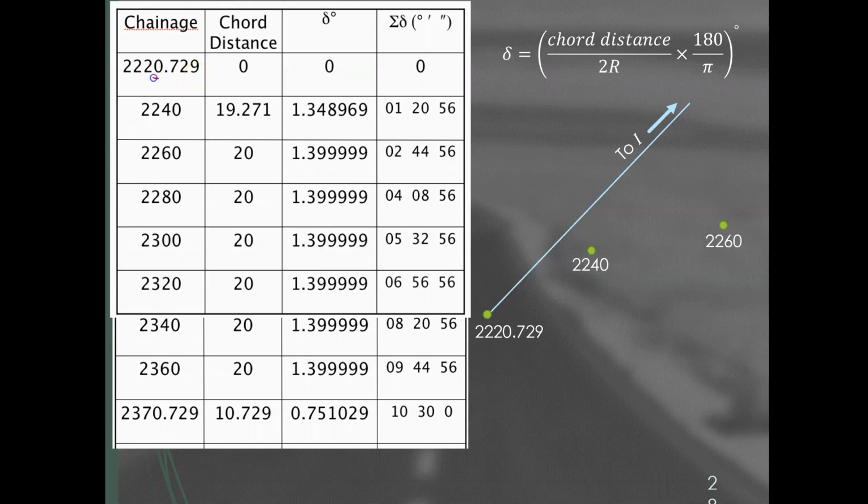So this is T1. For the next point after that, even though the question says the interval is 20 meters, when we do the marking on the ground, we work with round numbers in the multiple of the interval.